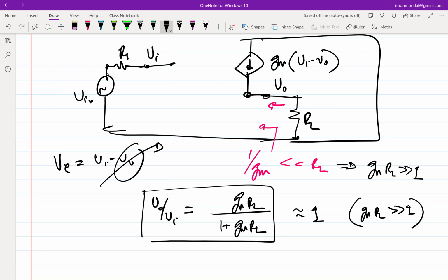If I don't have any tracking mechanism, if I don't have any error detecting mechanism, then V naught can go in its own direction, and VI can go in its own direction. So there has to be a coupling. There has to be a way to track the movement of V naught with respect to VI. One of the easiest ways to track is to see the difference. If the difference goes to 0, then perfect tracking. If the difference doesn't go to 0, there is no tracking.